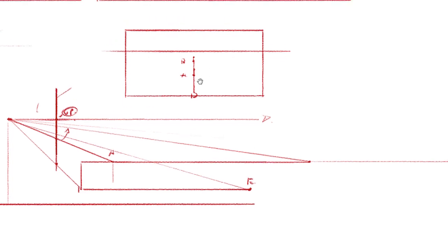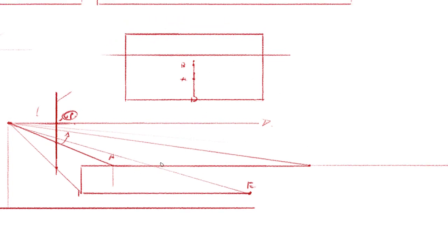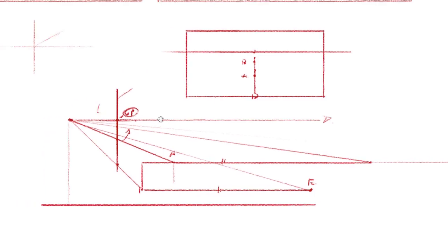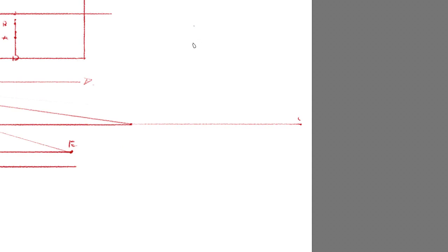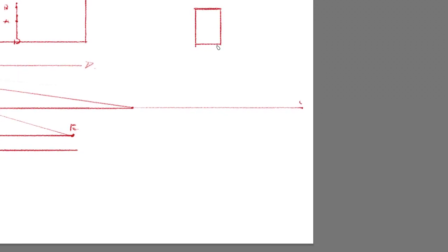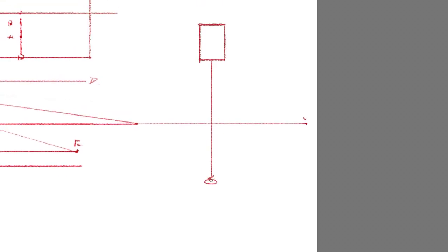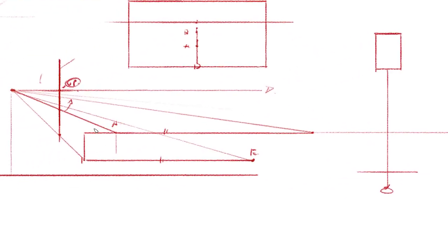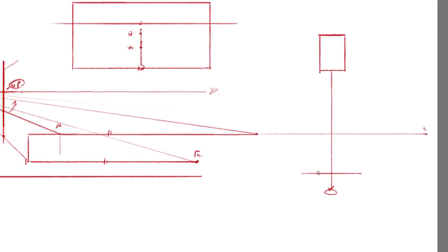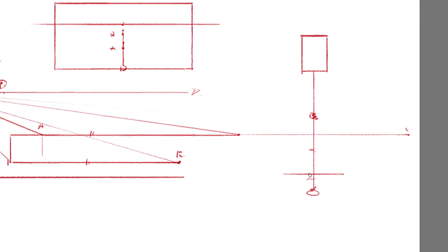Now if you can imagine these two lines, in this image they are parallel to each other, and still it's going up, up, up to the same vanishing point. Let's go into a side view quickly to see if this is true. Looking at my object, the box, straight on, this is the guy standing there, station point, picture plane. Because in the side view I can't go to the side, let's say line AB is this, AB, and now I'm going to draw a parallel line to this side.